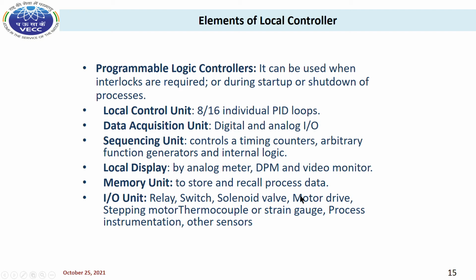The PLC sequencer consists of a master counter that has a range of preset counts. As it runs, when the preset count reaches a particular value, it can be used for control outputs. So each step in the count sequence sets a certain output or group of outputs.